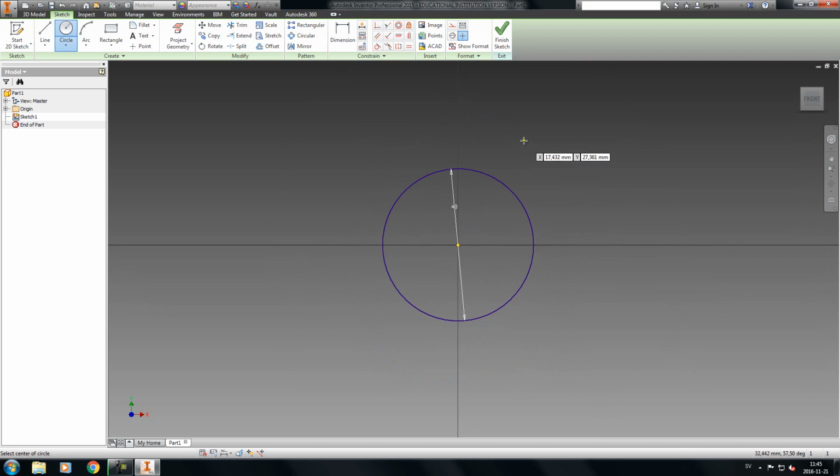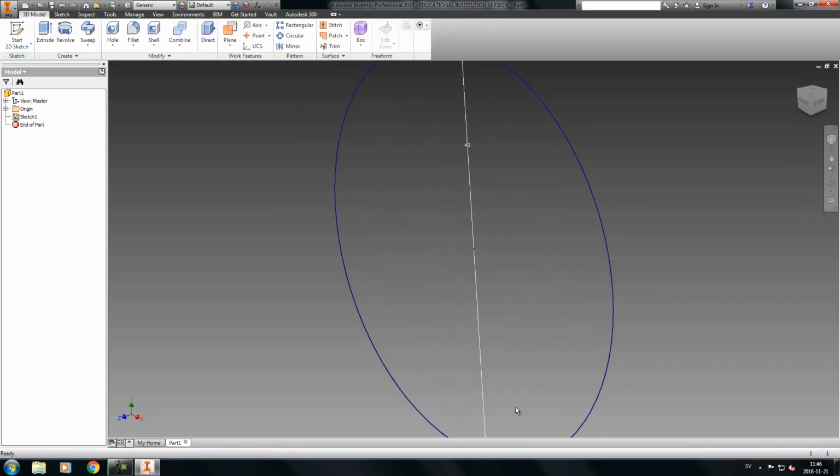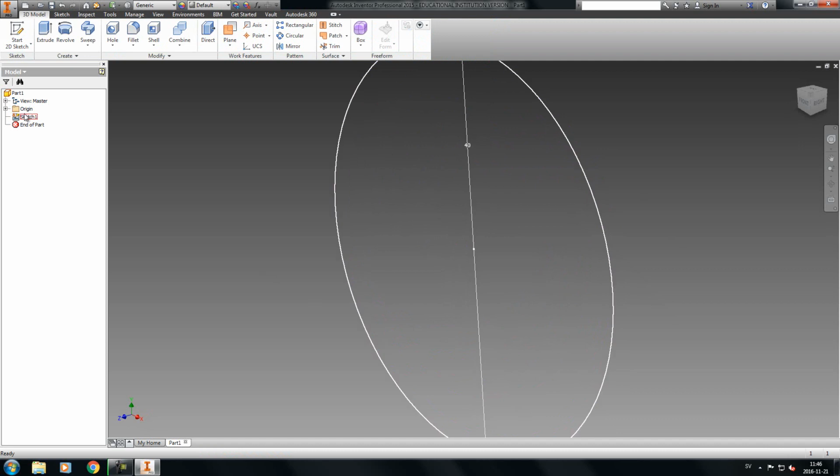Once you see this, right click and press OK to deselect the current tool. After that, choose Finish Sketch up in the top menu. You'll see that you're now back in the 3D view. However, you now have a circle drawn. It is also shown in the sidebar.